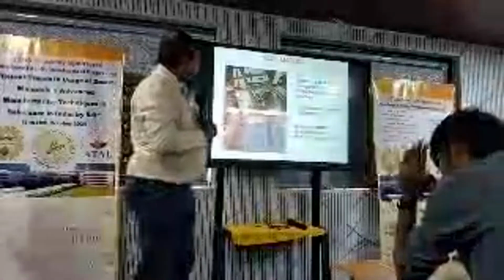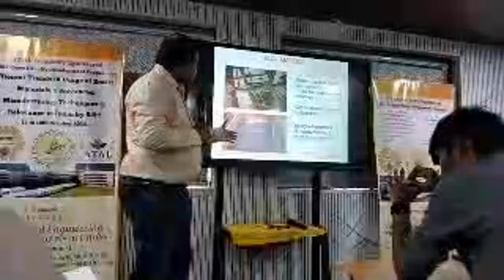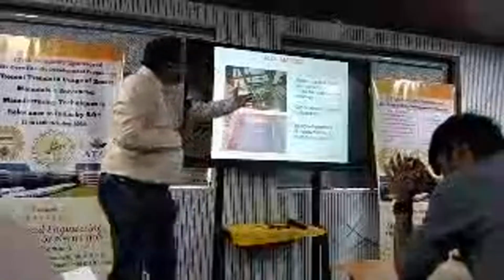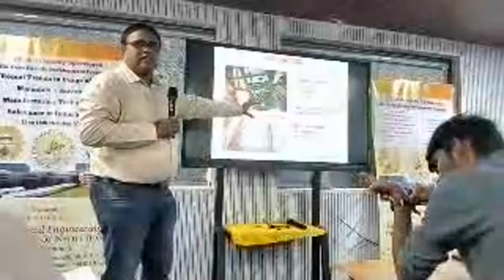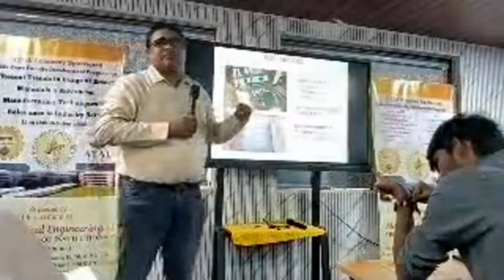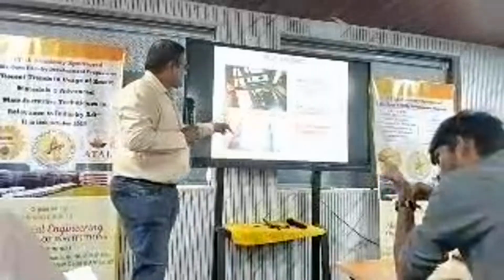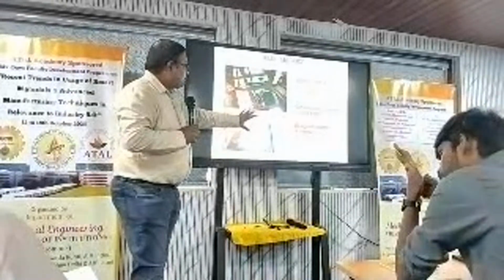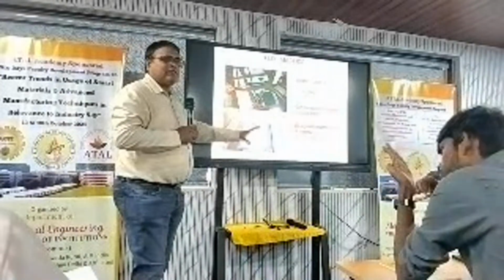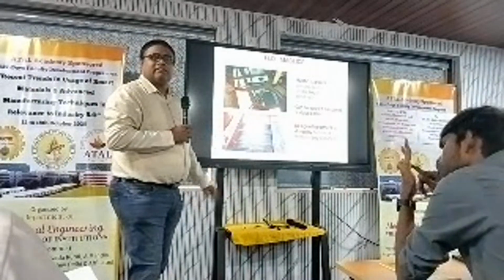That is what we have carried out. It is a paste-like structure, a viscoelastic material consisting of polymers as well as binders and pigments with some additives. The main crux is the composition. Only then can we decide and find out the vibration. So this will be applied, the vibration level measured before and after, and the reduction in levels observed.